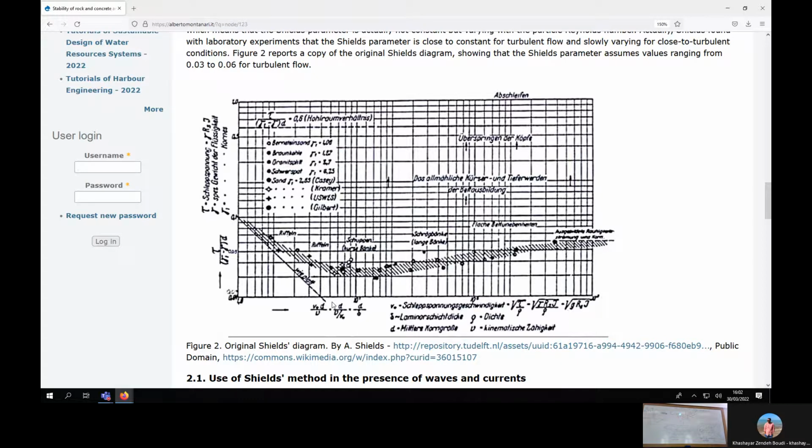The Shields results are for angle beta that is close to 0. And second, there is the effect of hiding. We studied here a single unit on a flat slope. This is not the situation that we have. We have several units that hide each other. And then there are empirical corrections that we will see after a break of 15 minutes.